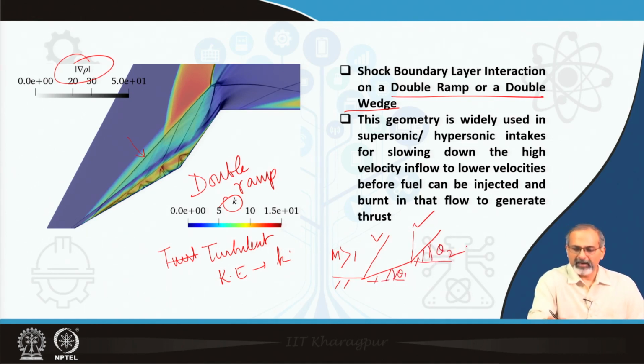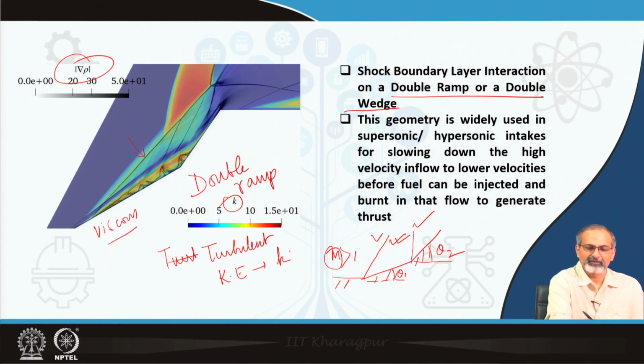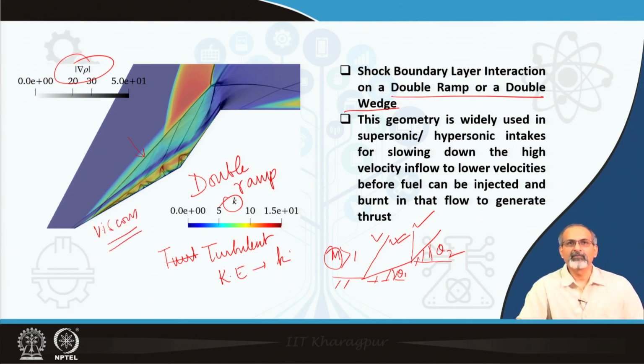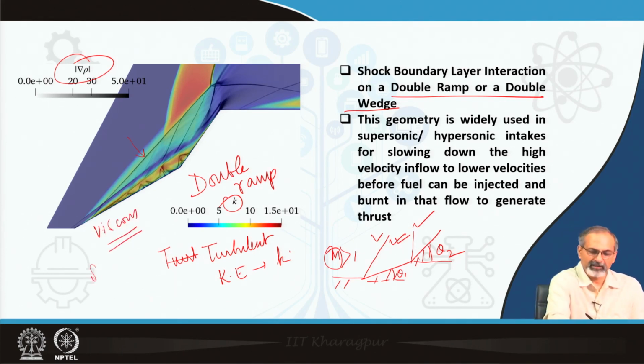If they at this given Mach number provided attached straight oblique shocks, then they would actually look like this, where the shock propagates from the wall. Always keep in mind that in the case of a viscous simulation, the shocks would never reach the wall. They can at most percolate up to the sonic line.